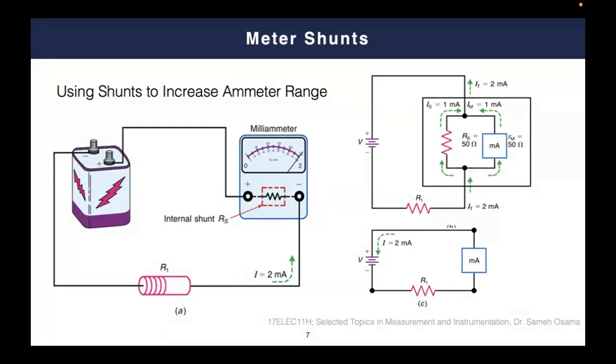Herein, for example, we have a coil. This is the coil, and the maximum current that can flow in the coil is 1 milliampere. The equivalent resistance of the coil is 50 ohms. So herein, a 50 ohm coil, this is the equivalent resistance of the coil, with a maximum current of 1 milliampere. That automatically leads to the maximum current that can be measured by this ammeter being simply 1 milliampere, which is the maximum current that the coil can withstand.